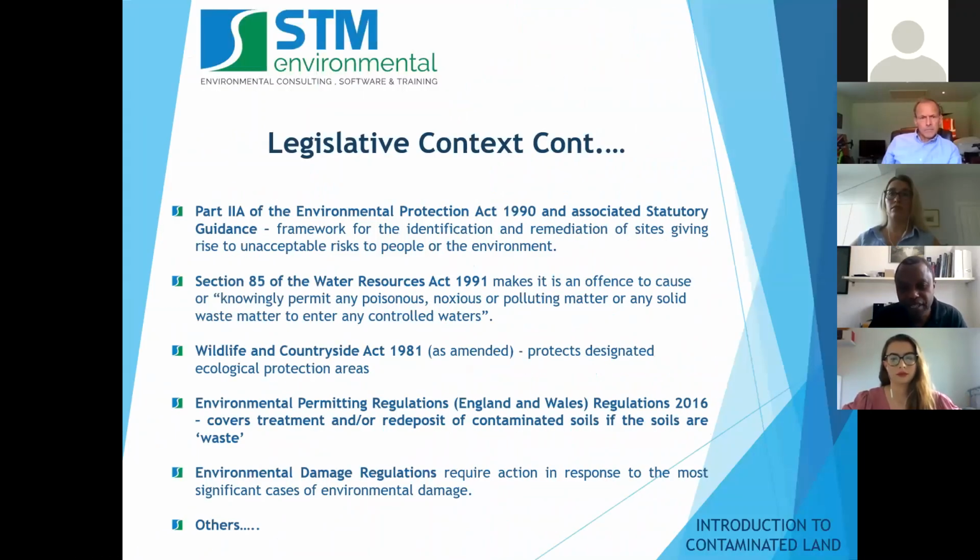Then we've got specific legislation that's designed to enable authorities to deal with actual contamination that's occurring, ongoing contamination. So you have Part 2A, which I touched upon earlier, Part 2A of the Environmental Protection Act. Essentially that gives authorities powers to go in and serve notices, requiring people to clean up sites. The Water Resources Act gives the Environment Agency powers to enforce decontamination of sites that are polluting controlled waters, so that would be groundwaters or surface waters.